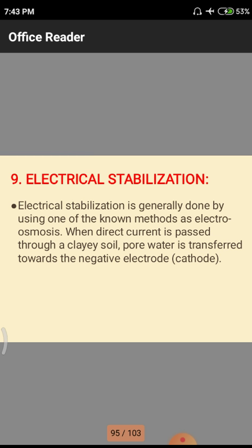Why? Because fly ash is obtained very cheaply, and everywhere nowadays. Moreover, every district has thermal power plants or other coal based waste materials. All those come under fly ash, so this fly ash is utilized for the purpose of stabilization.